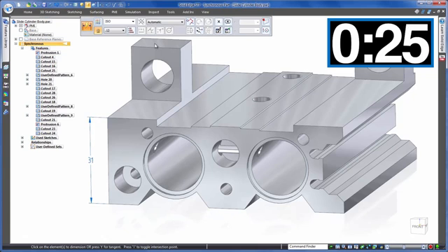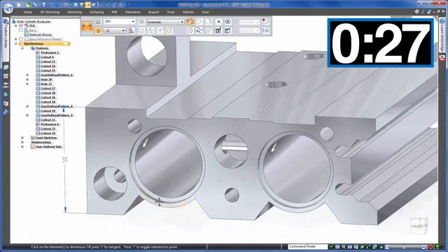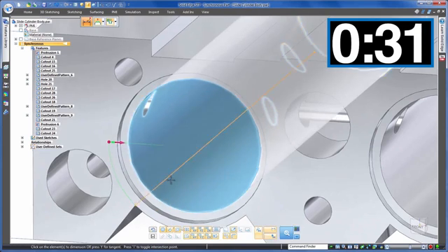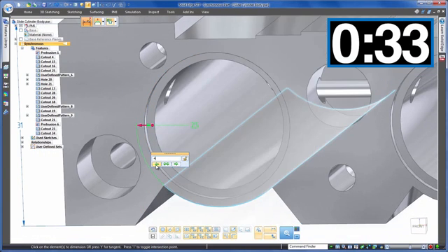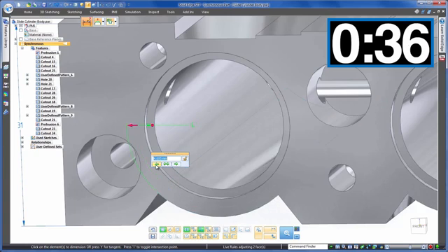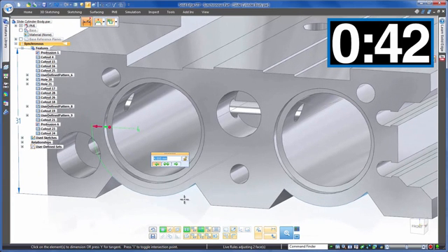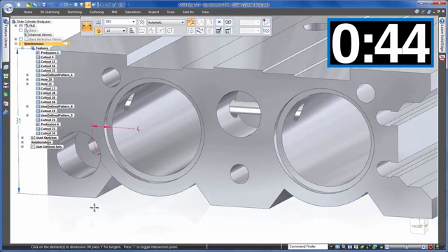The same change using synchronous technology, and dimensioning the two radii here isn't limited to just taking a measurement. Instead, we can immediately type in the 4mm clearance value required. As for design intent recognition, not only does Solid Edge allow us to add material rather than shifting the cylinder slides up, but it also recognises that we'd want the other side of the model to change too, as it's symmetrical.